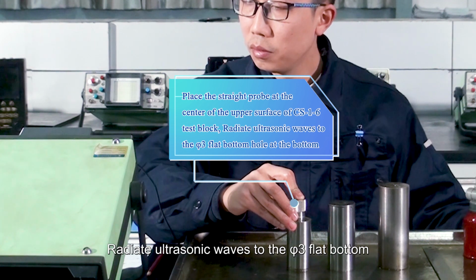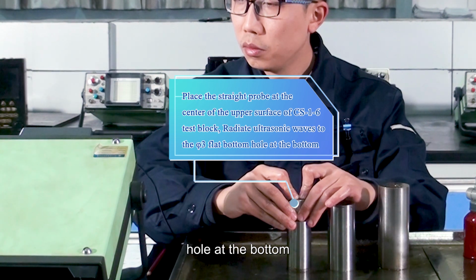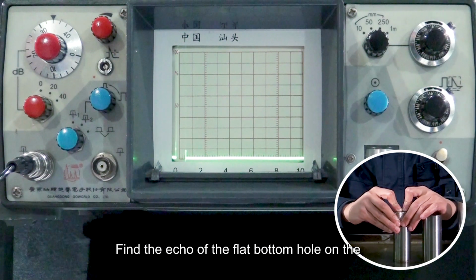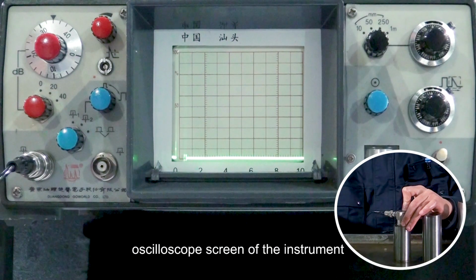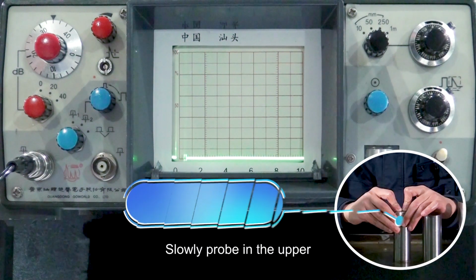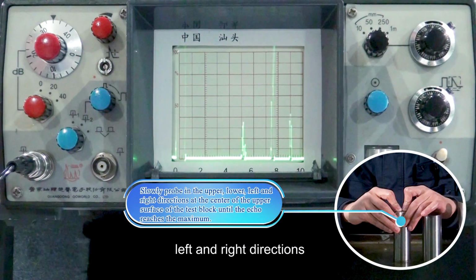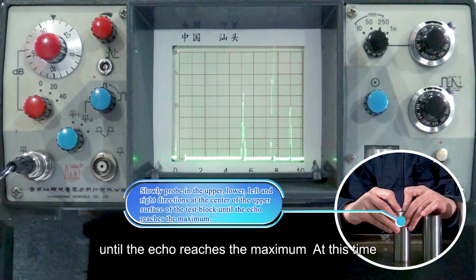Radiate ultrasonic waves to the flat bottom hole at the bottom. Find the echo of the flat bottom hole on the oscilloscope screen of the instrument. Slowly move the probe in the upper, lower, left, and right directions at the center of the upper surface of the test block until the echo reaches the maximum.